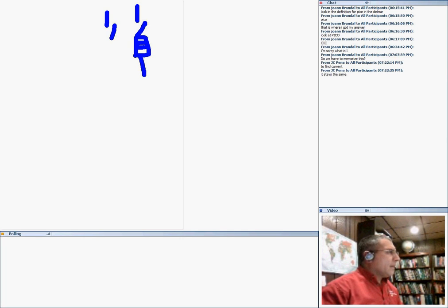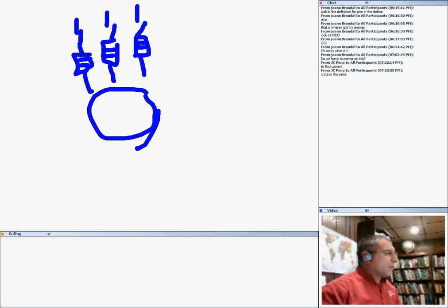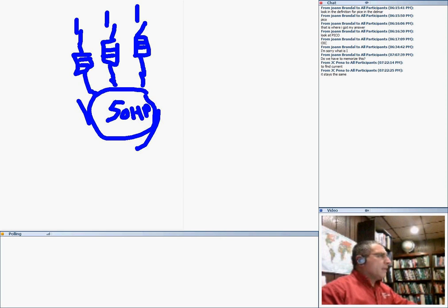Here's phase A, here's phase B, guys, and here's C. Three phases, and from this side I'm going to deliver that power across my motor. My motor here, my 50 horsepower motor, right? I want to bring your attention to a couple of things here. I want to bring your attention to the disconnect. Look, the disconnects are connected in series, as the fuses are connected in series.